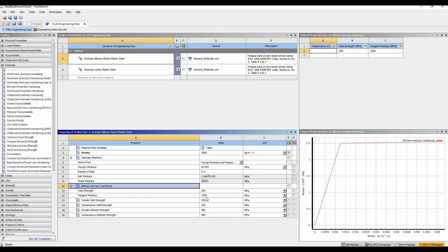So notice that the plastic modulus is very small, it's just 1000 megapascals, when the Young modulus in the linear regime is 200,000 megapascals. So this is almost an elasto-perfectly plastic model, because this is very, very close to the horizontal line we saw in the theory before. But anyway, it presents certain hardening, because there is a slope, there is a value for this tangent modulus, so it's going to be able to capture the change in the yield strength when we load and unload our bar.